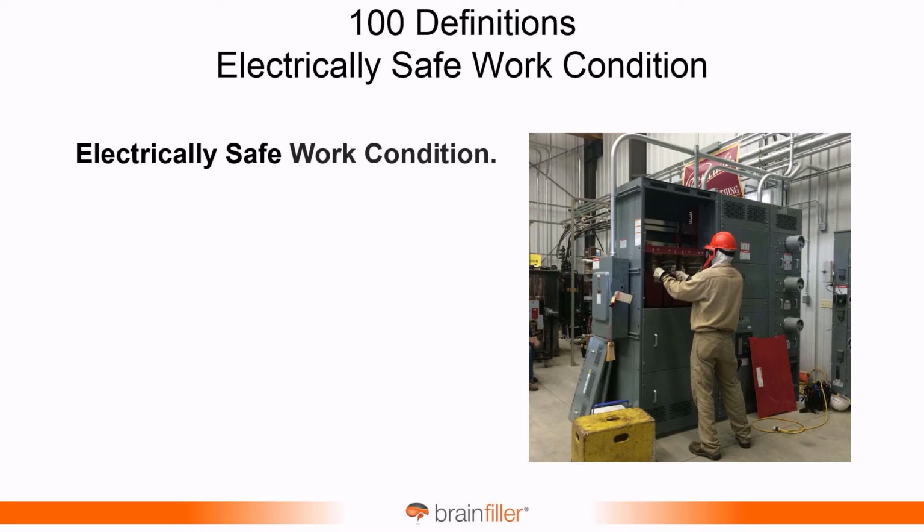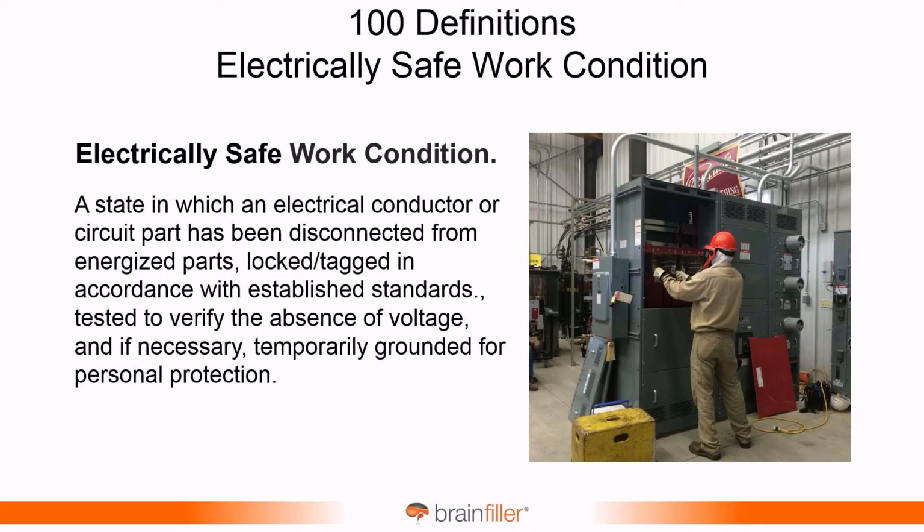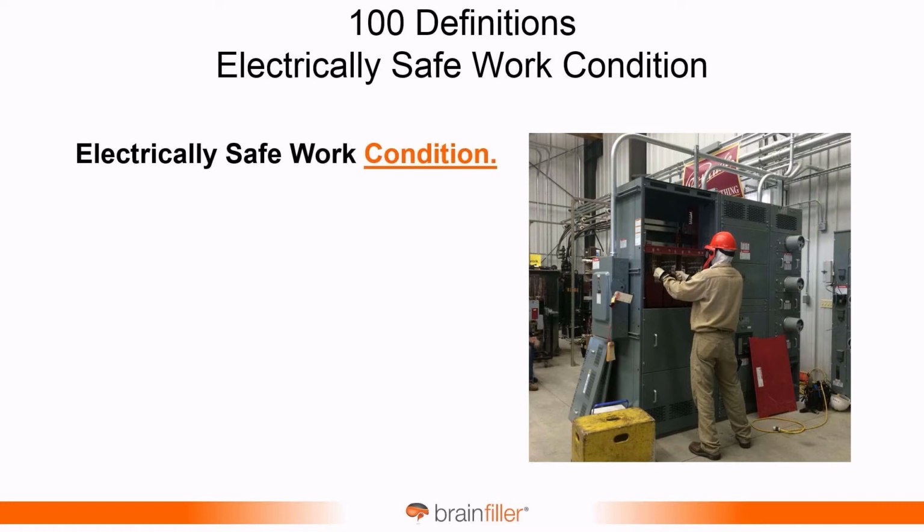The electrically safe work condition. This is quite an important change. I talked about the theme, as I referred to it, and how the electrically safe work condition is this reoccurring theme, and it keeps getting elevated to a higher and higher level. There was a significant clarification. I don't want to say it's a major change, but it's a clarification to the term electrically safe work condition. This is the definition as we've had it, and it's a state in which an electrical conductor or circuit parts has been disconnected from energized parts, and we know the rest of this. But what has been clarified is the word condition.